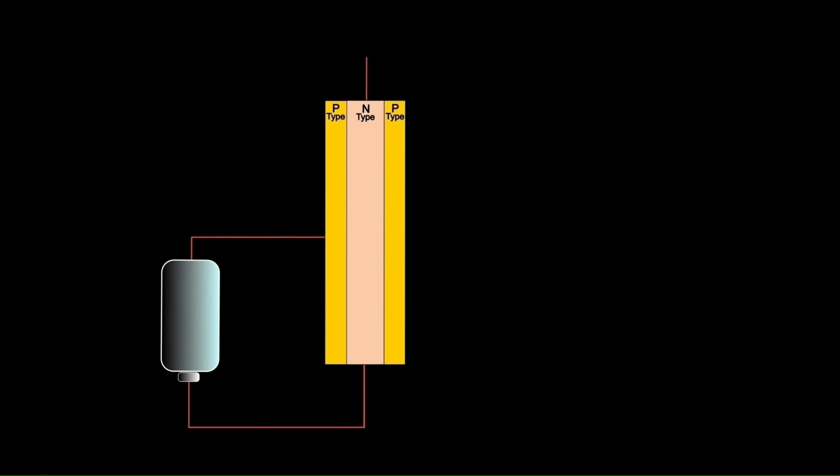of N-type material and add a third wire to these new layers, we find that we can now vary the conduction through the central N-type material. This happens when a negative voltage on the P-type material causes the electrons in the central region to move away and create a depletion region. In this depletion region, there are few charge-carrying electrons, so the resistance appears higher when there is a negative voltage on the outer material. It is the electric field that causes a shortage of charge carriers.